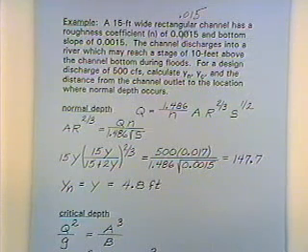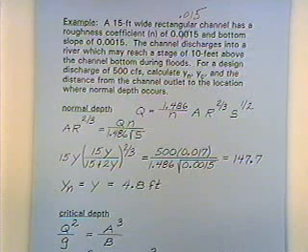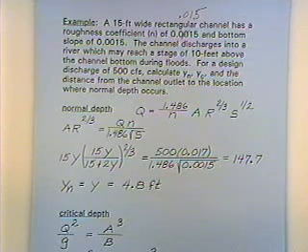Now, if you get far enough away from the river, you can use Manning's equation. It's a prismatic concrete channel, with a constant bottom slope of 0.0015, a constant bottom width, a constant rectangular channel section. So we can use Manning's equation to compute the depth. However, the backwater effects from the river into which the channel is discharging cause a non-uniform flow situation.